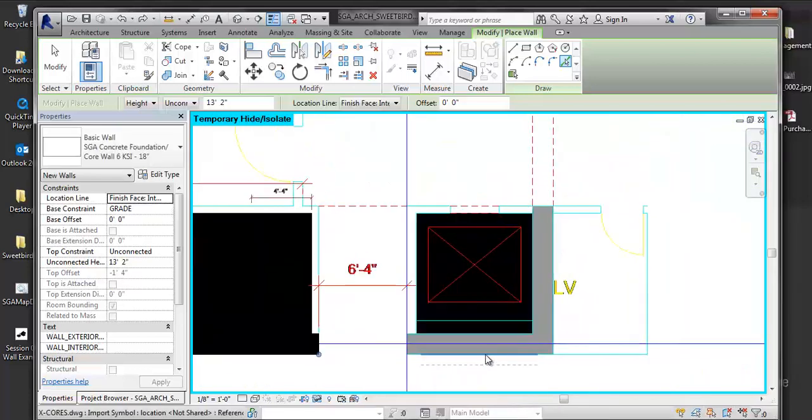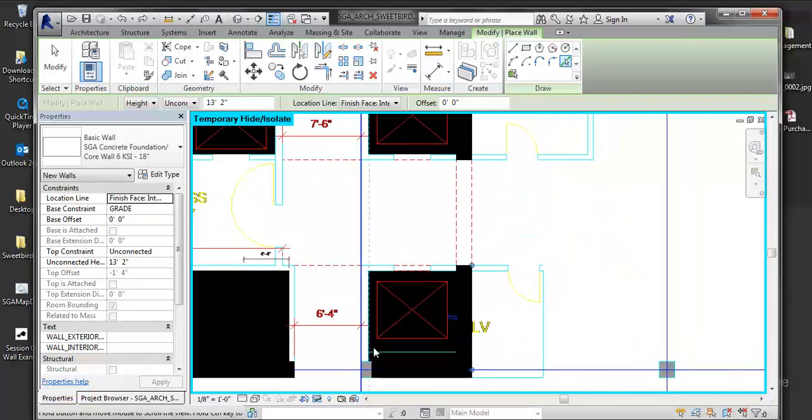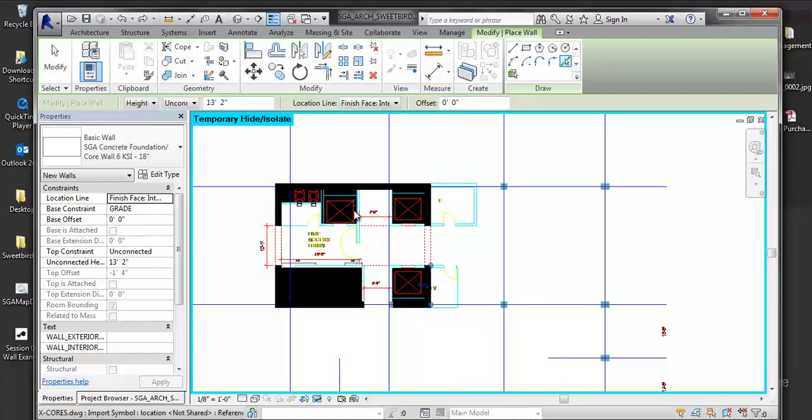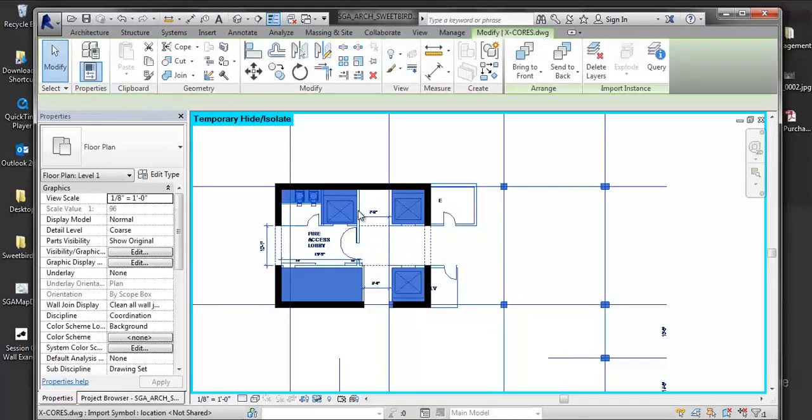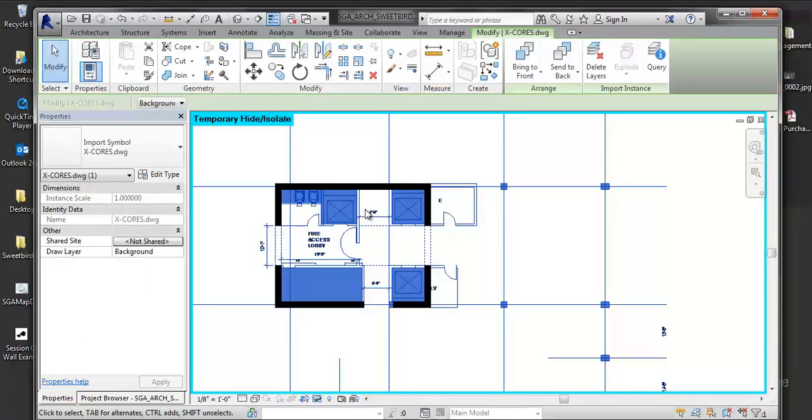Now you'll notice one thing about using these, and what really bugs me, is at least doing this from CAD plans, taking somebody's CAD plan that doesn't necessarily know how Revit works. If I'm selecting my CAD plan, you can see what the walls look like. Now, you draft in CAD with wall openings. So we draw in plan, we say there's an opening, you put the dotted line. In our case, that doesn't help us at all, because we need to have that completely situated around it.